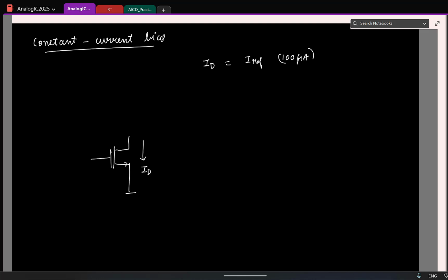So which means, let's say this is connected to something. Let's say it's connected to VDD itself. The current mainly depends on VGS. So I should be actually providing some VGS here so that it provides a current. But if I keep the VGS constant, if the threshold voltage changes, current will also change. Which means if I have to retweak my current, what should I be changing? I have to somehow change the VGS so that the current is constant. Is that clear? So somehow I have to keep it programmable.